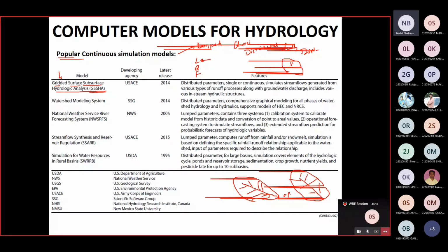Again, for the second tributary I can take a smaller area and measure the discharge at the second outlet. Then I will measure the next smaller area and its outlet. At the end, I will sum all these discharges from the various outlets, and combining them, I can calculate the runoff.